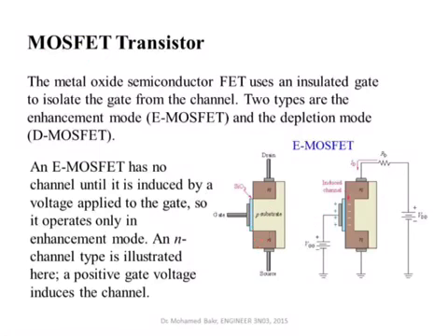Okay. So here, when you don't apply any voltage between the gate and the source, there can be no conduction flowing here, because here you have a lot of electrons, here you have a P-type material. There is no conduction channel here. There is no continuous region of N-type material where electrons can flow. So the way to get around that is simply to apply a positive voltage on this capacitor. This looks like a capacitor.